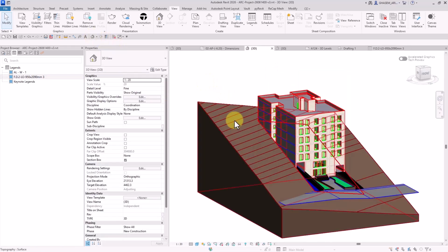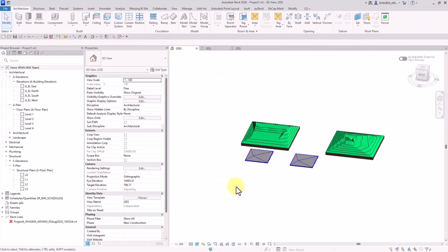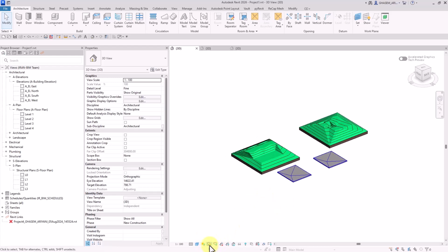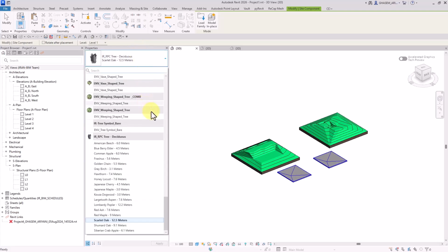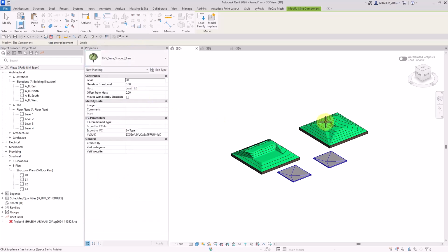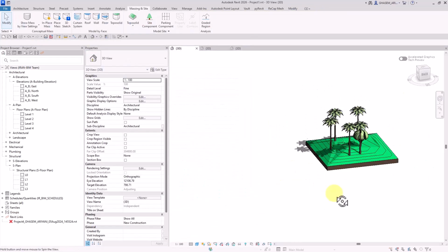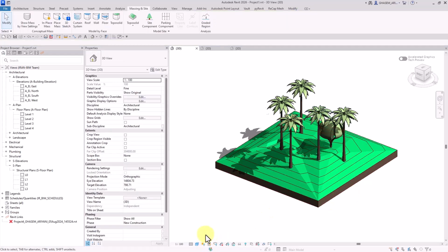Now, I'm going to go back to the 3D view, maybe this one that is lighter. I'm going to activate shadows. Here, turn them on. You know what, let me add an object here in order to get the shadows. Alright guys, now I'm going to go ahead and activate Solo Study down here.